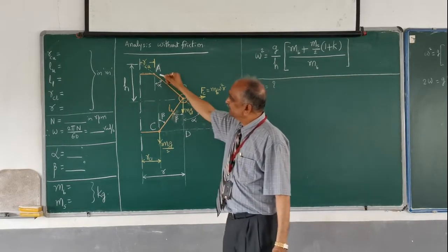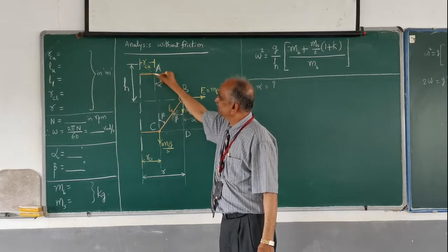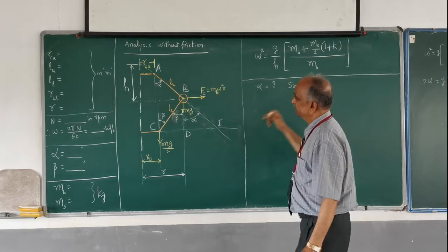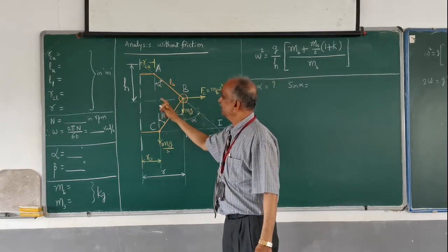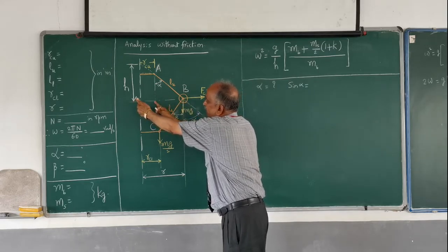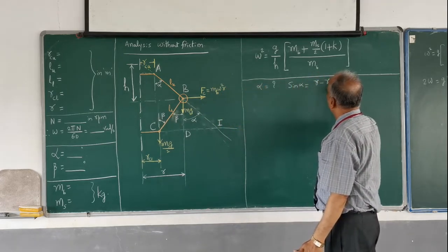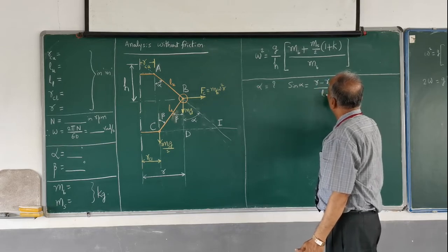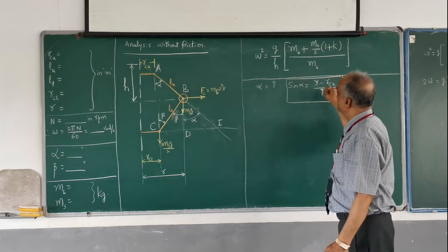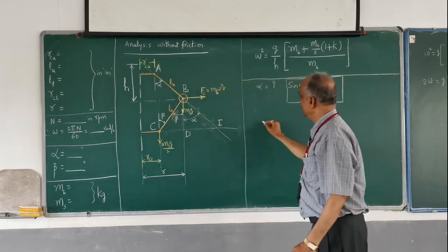So go back to this diagram and make use of this triangle. If I write down an expression, sine alpha is equal to this value. And what is this value? That is nothing but the radius of rotation, r, minus this value, that is nothing but r_cu. So sine alpha is equal to (r minus r_cu) divided by L_u. This will give you sine alpha. So knowing these values, you can find sine alpha, and from that you can easily find the value of alpha.